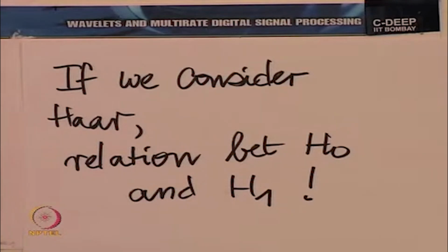In fact, what we are trying to say is, we of course need to relate the synthesis to the analysis for the purpose of alias cancellation. But now we have a perfect reconstruction requirement. So, we want this tau 0 z to essentially go to a delay and a multiplying constant.